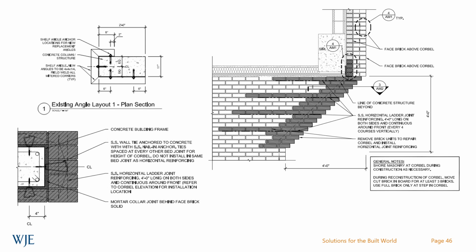And these are the repairs that we developed, rebuilding the haunches that exhibited the cracking from a combination of corroding steel and inadequate structural support. We came back in with reinforcement in the cantilevered portion of it that was tied back in to the main body of the haunches to provide a lateral restraint for the cantilevering of the haunches.